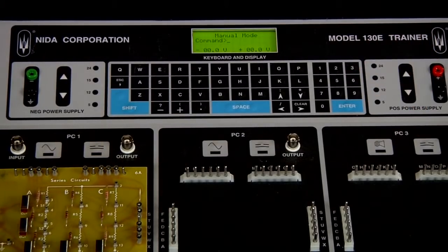The other way that we can clear faults from a particular card slot is to just use 0, 0 for the fault number, and for that particular position, in this case we would use the C and position 1, and then enter in the 0, 0. Any faults that would be programmed in for that particular PC slot would be eliminated. So we'll be back to the no faults for that particular position.